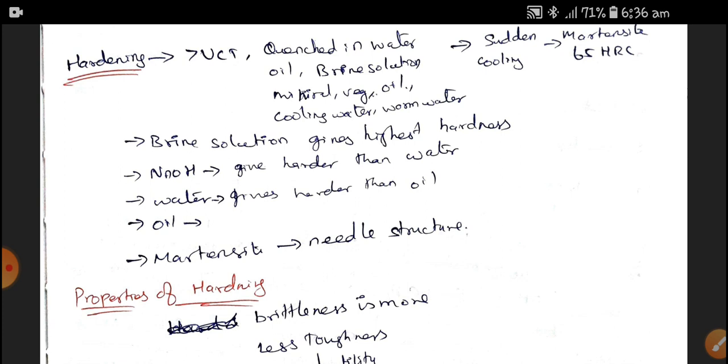Those new grains are suddenly quenched. We do not want the new grains to elaborate and combine. Therefore, sudden cooling happens here. With the sudden cooling, the material becomes much harder, and a martensitic structure forms.